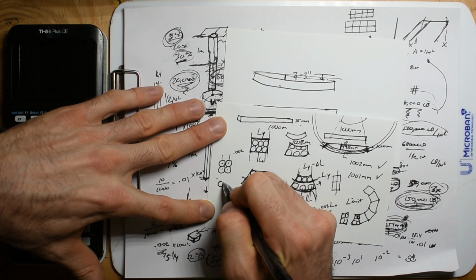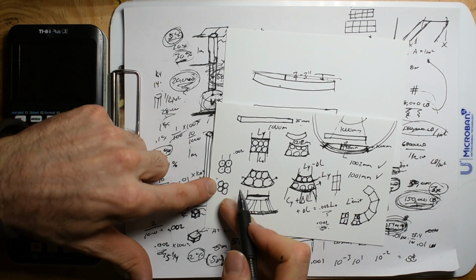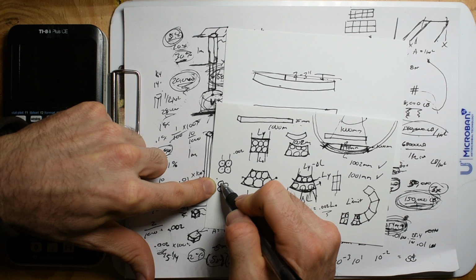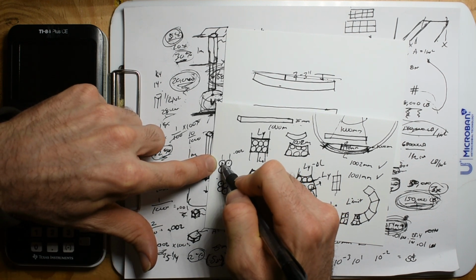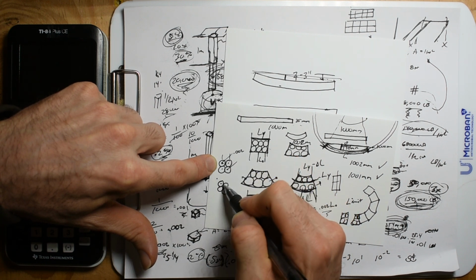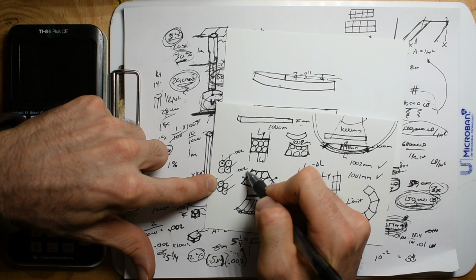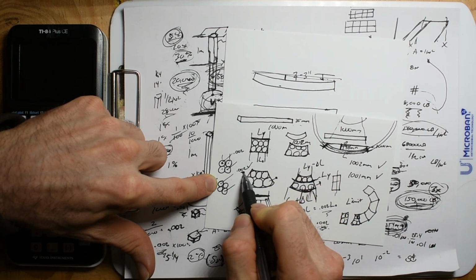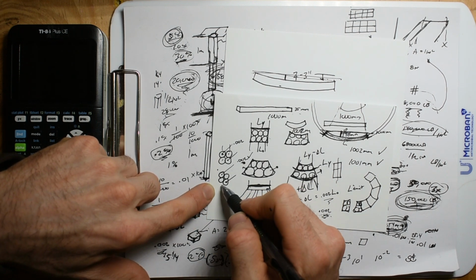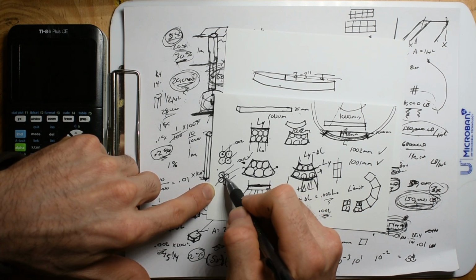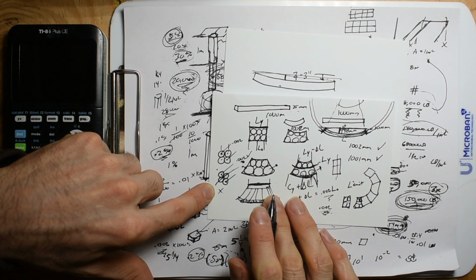And so when we shear something, what happens is this goes down and this stays put. Now, you can see the distance between, and even diagonal distances. If that distance is right there and there, this can't increase. And you can even visibly see this increased. And 0.002, just keep in your mind that that's really a small change in length. So this is over-exaggerated, and we would have a break right there. These two molecules would snap away from each other, and they break at a 45-degree angle.